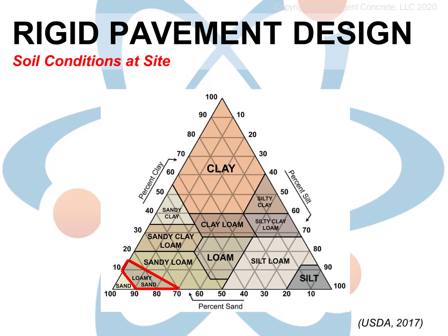How this chart is used is that a person would look around the triangle to find their soil descriptor. Its location on the chart gives the various percentages of sand, silt, and clay. As you can see, our soil is 70 to 85% sand, 0 to 15% clay, and 0 to 30% silt.